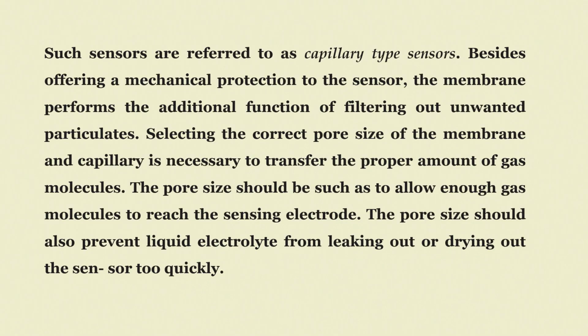Actually, what is to be controlled is the pore size. That has to be large enough to allow gas molecules to reach the sensing electrode, and the pore size should also prevent liquid electrolyte from leaking out or drying out the sensor too quickly. So, quite often we use zeolites. Zeolites are known to have very specific pore size that can allow known gases of particular type, molecular size, to pass through the membrane.